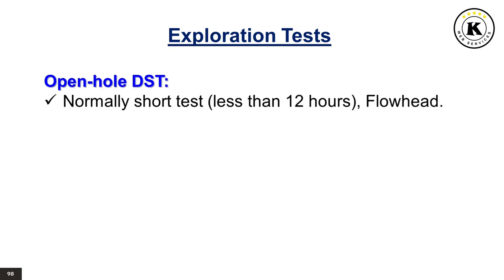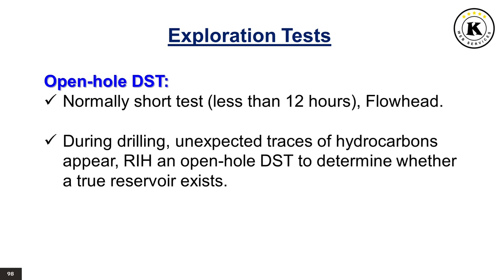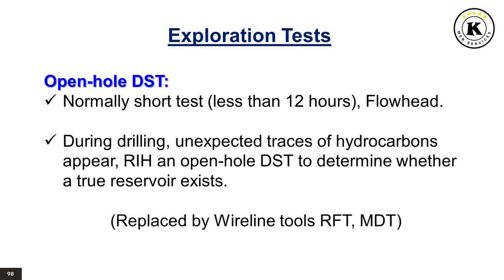Exploration tests. Open hole DST. Normally a short test, less than 12 hours, using flowhead. During drilling, unexpected traces of hydrocarbons appear. Run in hole and open hole DST to determine whether a true reservoir exists. This type of test is now replaced by wireline tools such as RFT and MDT.